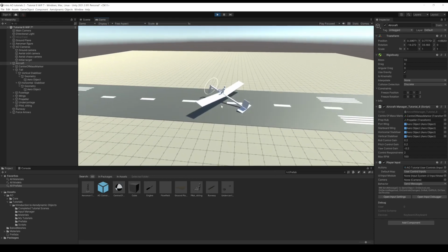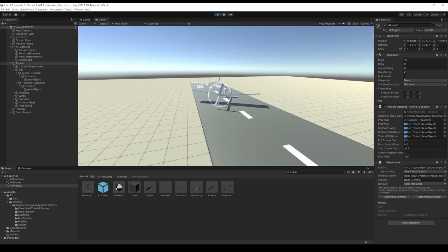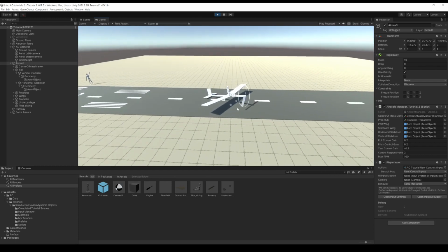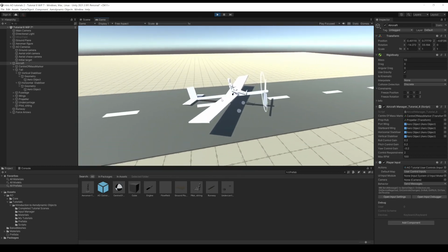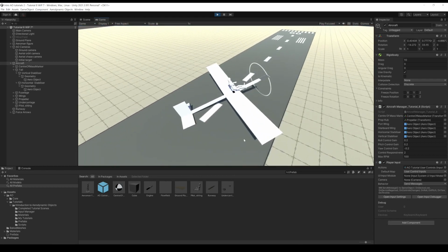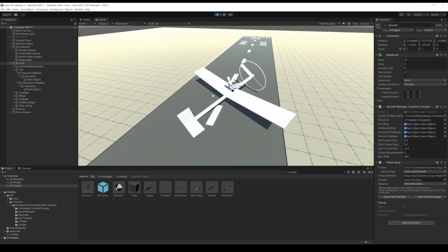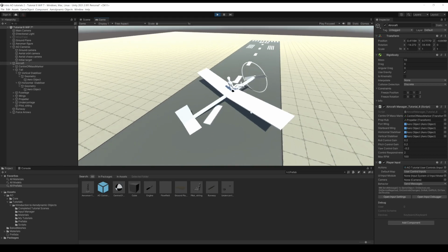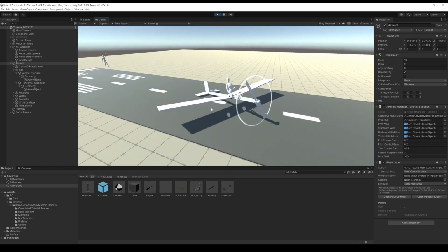And so what we've seen there is that you can put an aircraft together out of fairly simple bits. There's nothing moving on here in terms of controls, but what we're doing is varying the aerodynamic camber of these surfaces to simulate a flight control surface. So we've got our ailerons by altering the camber of the wings, we've got pitch control, and we've got yaw control, and combined together we've got a fully serviceable flight vehicle.